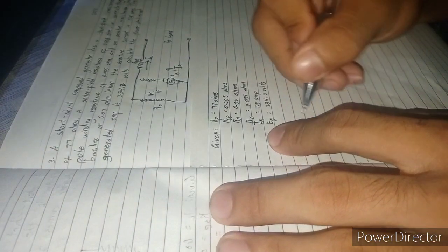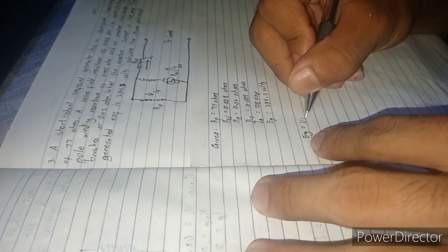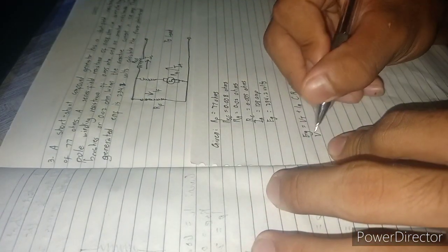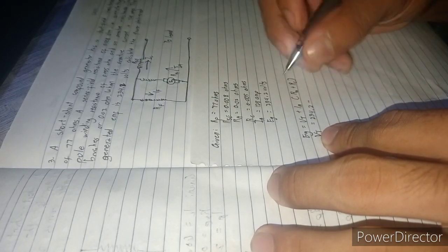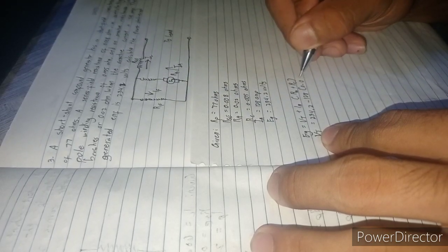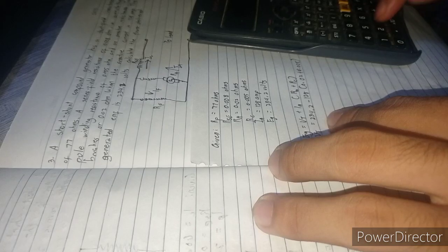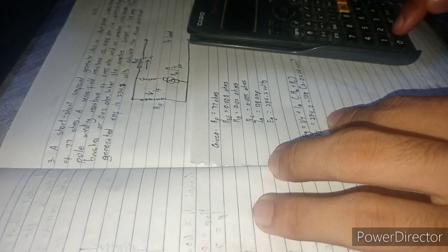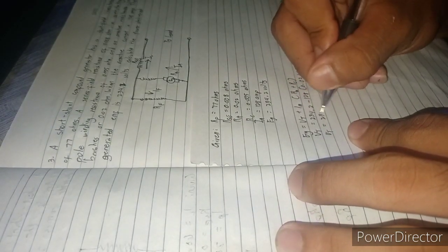Then, EG is equal to VT plus IA times RA plus RC. Deriving for VT, it is equal to 234.2 minus 128 times the quantity 0.02 plus 0.005. Calculating, the answer is 231 volts. So VT is equal to 231 volts.